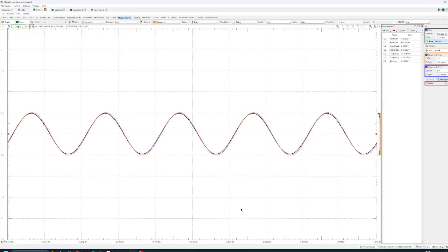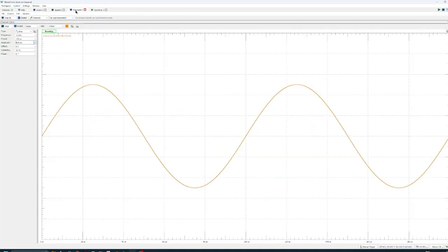Moving on, one way to find the mid-band gain as well as linearity is to go over to the wave gen and play with the amplitude to see if anything changes. Let's try two different values. What we saw before was with 500. Let's try 200.